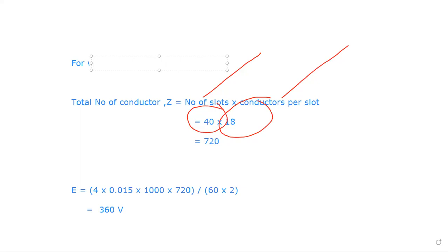Okay, wave winding is a type of armature winding in the direct current electrical machine such as a DC generator or DC motor. It is one of two primary winding configurations, the other being lap winding. In wave winding, there is one coil per pole and double the number of commutator segments.